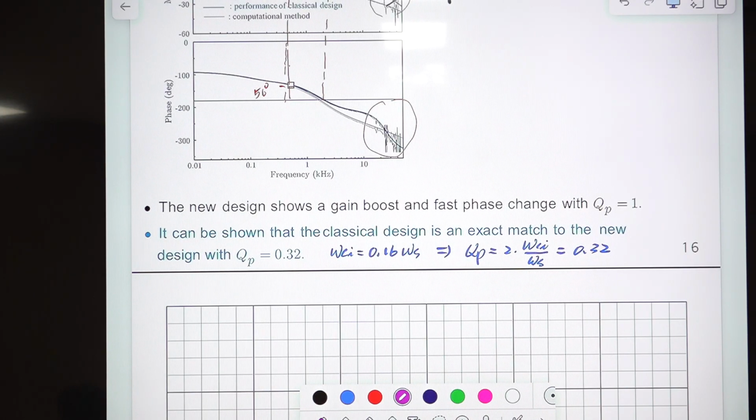Everything remains almost the same except that compensation ramp slope. This also highlights the importance of the SE, and also highlights the limitation of this control method. There is one variable which we can play with in here. Right?